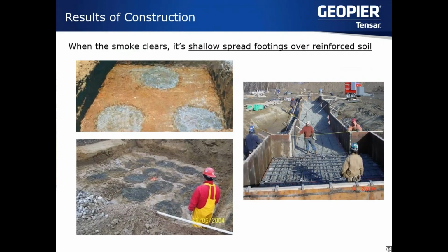But at the end of the day, whether it's an aggregate pier or rigid inclusion, we're providing a solution which reinforces the in situ soil and allows standard shallow spread footing construction to occur. So we talked about the fact that we're not structurally connecting any of these two foundation elements. They're simply there to improve the bearing capacity of the in situ soil and control settlements.